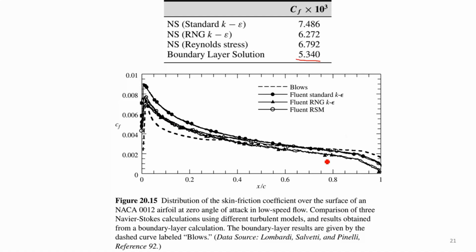The difference between different turbulence models can be big or not significant, depending on the application. As I already told you, some turbulence models are better than others on very specific tasks. And we must remember also, even for Baldwin-Lomax, for example, that the model has several coefficients inside.